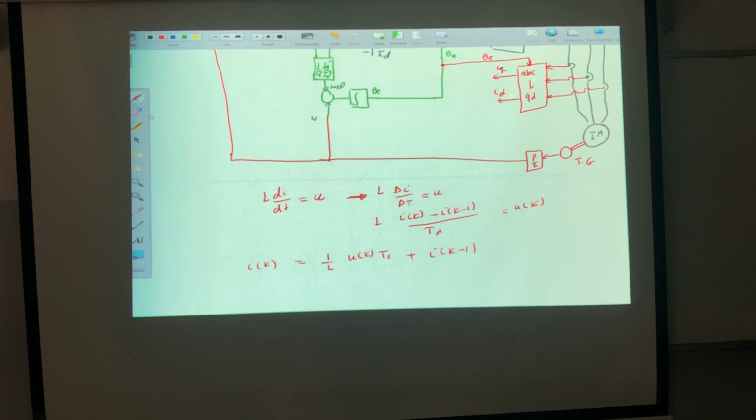Now, in general, the alpha beta, for example, reference frame, which is the stationary reference frame. The stationary reference frame simply will transform the three-phase system to a set of orthogonal systems, the alpha beta. The alpha beta reference frame. Now, in the end of the day, any used reference frame will either contribute in understanding the physical system or make the controller easier to deal with. Is there anything easier to control than synchronous? No, this one is, I think, the easiest one to control the induction machine.